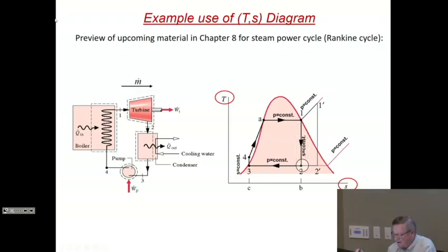You expand it in a turbine. Well, this turbine is supposed to be internally reversible, ideally. So that means that it actually happens at a constant entropy, so it's a vertical line here. Well, that gets you a point where there is a certain amount of quality to your steam. So there is gas and liquid present here, which we then condense fully at 0.3.